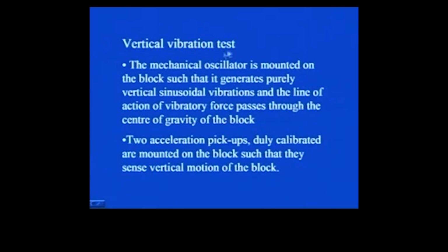As the name of the test suggests, it is the vertical vibration test. So the mechanical oscillator which has been mounted on the concrete block is mounted in such a manner that it generates the oscillation in the vertical direction, that is vertical sinusoidal vibration, and it will be creating the external force which will be acting on that particular block.